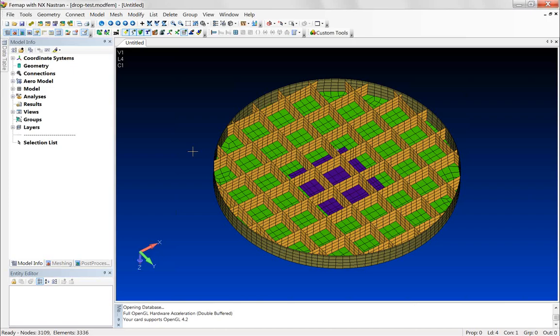And for this demonstration, what we're going to try to do is demonstrate a script that works by generating and assigning new properties to elements in all the selected groups of the model. So the point of this is to use the API to help me turn each of these orthogrid webs, each of these members that crisscross each other, and turn them into unique property zones. And one use for breaking up the model in this manner is to allow optimization software to uniquely size each property to get as much mass out of the model as possible.